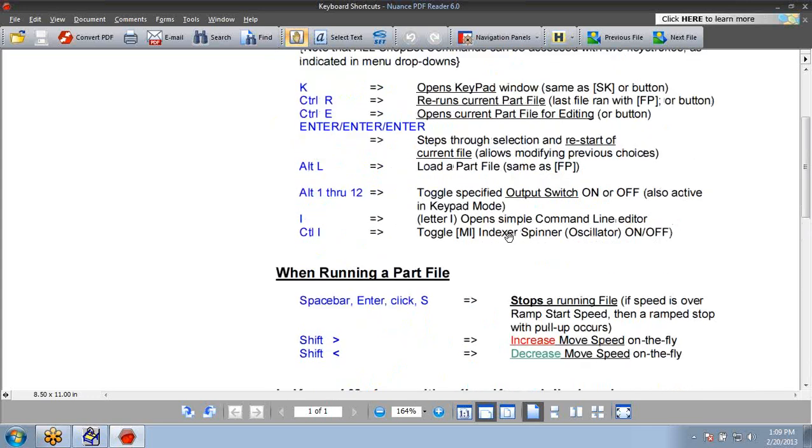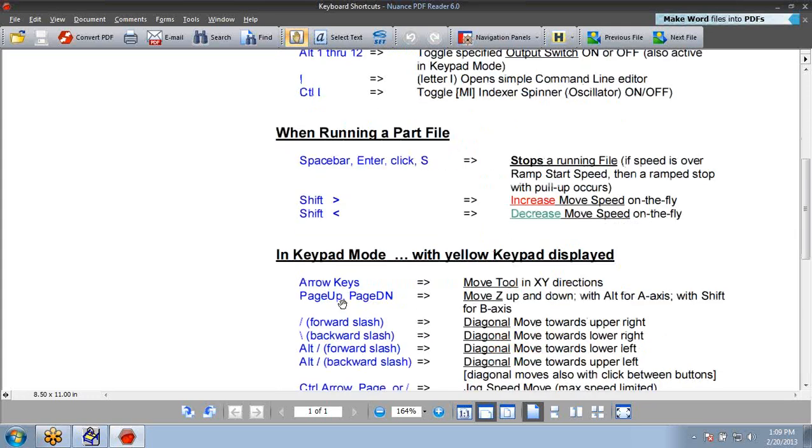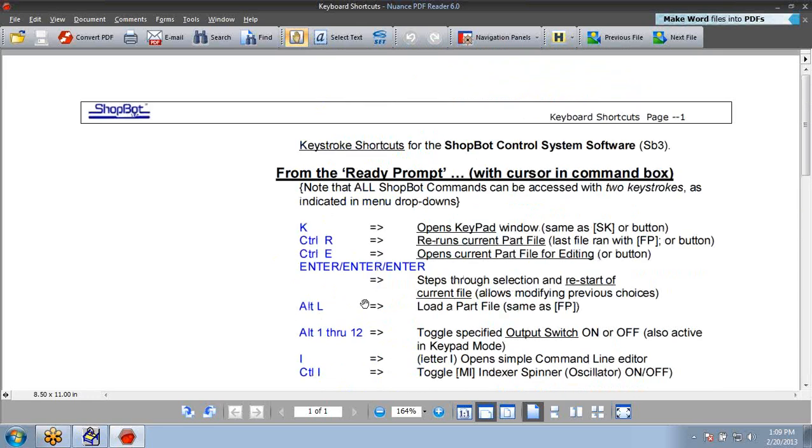Now note, it's not going to save your PartWorks file with these settings. So I always recommend still, if you see it's not cutting quite right, stop it, go in and fix it, resave your toolpath and your file, and then come back out. But if it's something you got to fix on the fly, go ahead. Here's some of those key commands to get you through this.